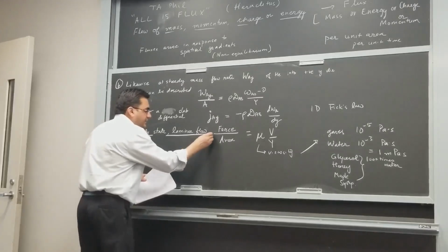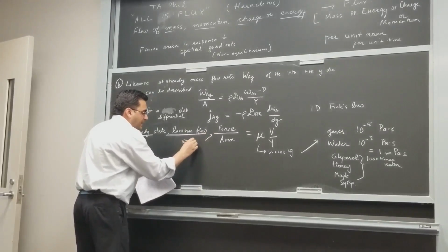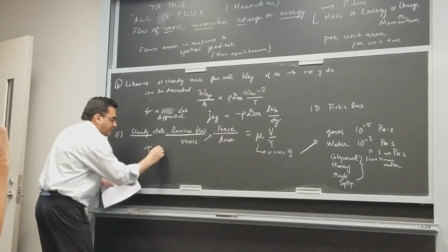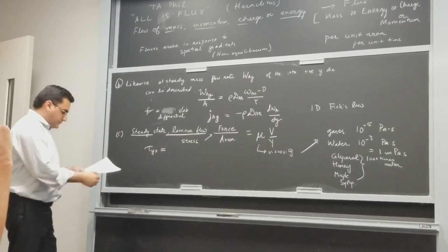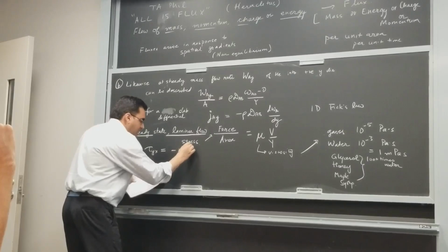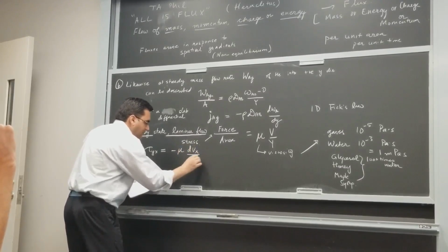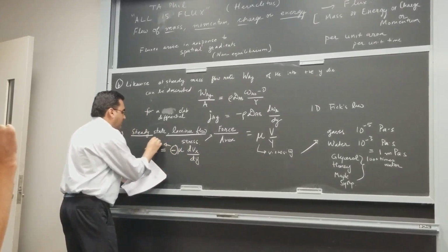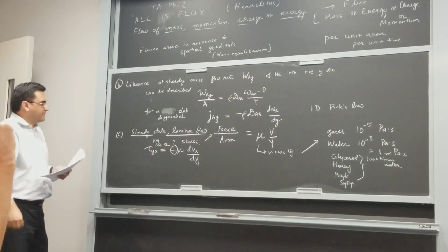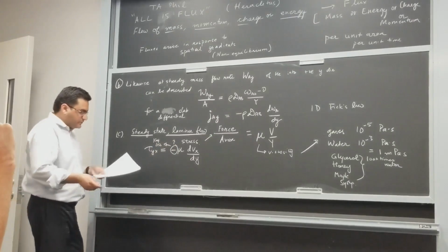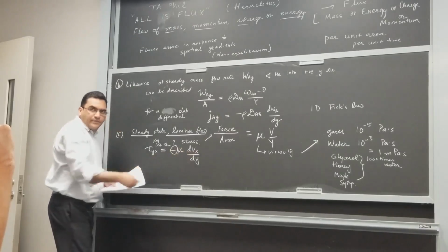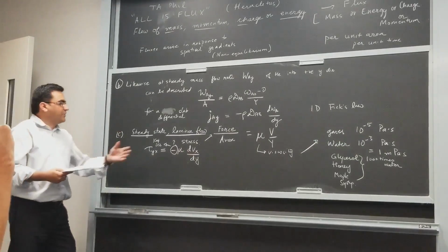So force per unit area is called stress, and you can write this as tau_yx, and we'll say why we use tau and why we use this notation. Keep it for BSL; it doesn't matter if you are not following BSL. So what you have here is flow in the x direction and gradient in the y direction. And that's a particular property of something we call shear flow.